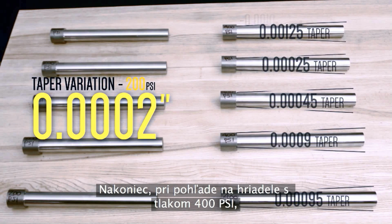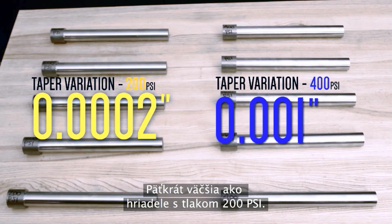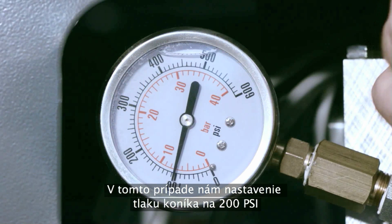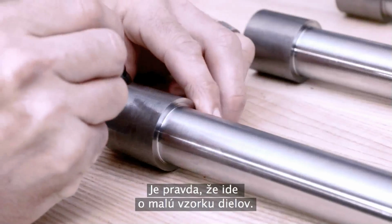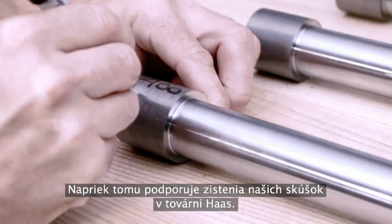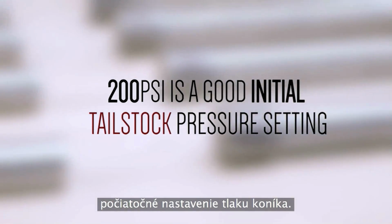And finally, looking at the 400 psi shafts, surprise! The taper variation is 1 thou, 5 times greater than the 200 psi shafts. In this case, setting tailstock pressure to 200 psi gave us more consistent results. Admittedly, this is a small sample of parts, but it supports what we found in testing here at the Haas factory. And we think it demonstrates that 200 psi serves as a good initial tailstock pressure setting.